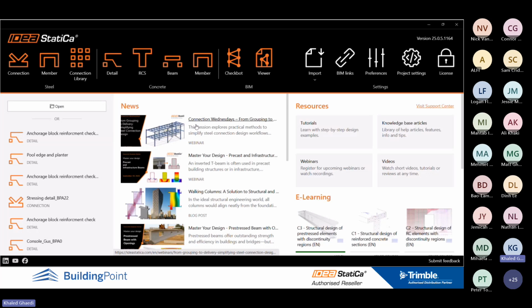So we applied the serviceability under short term. So here we have it. And also you can go to nonlinear deformation of the section, and from here you can play with the scale, just to feel the behavior of the section that you are designing. Okay, and also you can look at the tensor of stresses as well. So, let's say, the stress in direction 1 and direction 2, and also the strains. And again, you can look at the direction of the stresses for tension and compression stresses as well, or zones. And finally, you can go to the report.